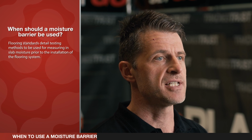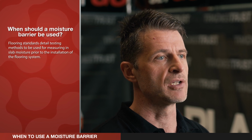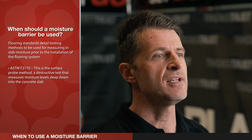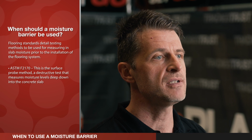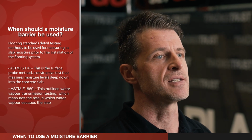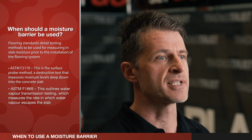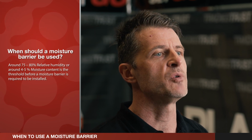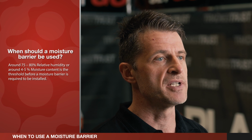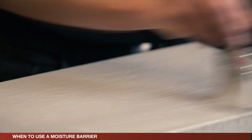Each standard details testing methods to be used for measuring in-slab moisture prior to the installation of the flooring system, including ASTM F2170. This is the surface probe method, a destructive test that measures moisture levels deep down into the concrete substrate, and ASTM F1869, which outlines water vapor transmission testing, which measures the rate at which water vapor escapes the slab. Around 75 to 80% relative humidity, or around 4 to 5% moisture content, is a threshold before a moisture barrier is required to be used. Of course, moisture barriers can be applied purely as long-term preventative or precautionary measures, regardless of current moisture levels.